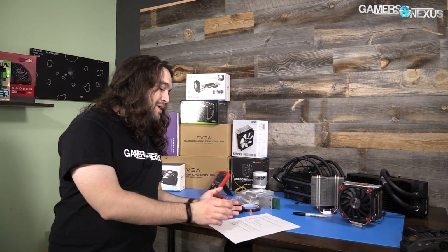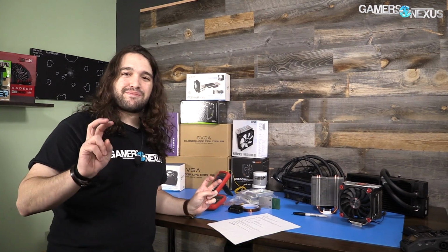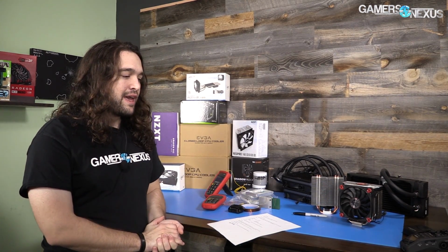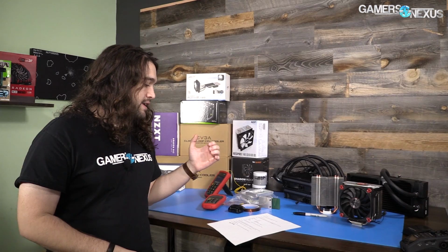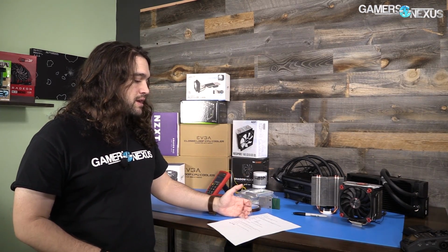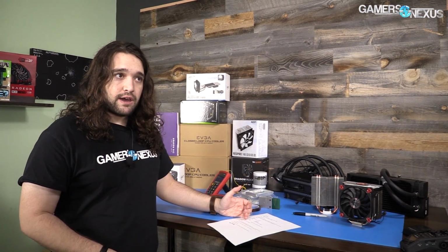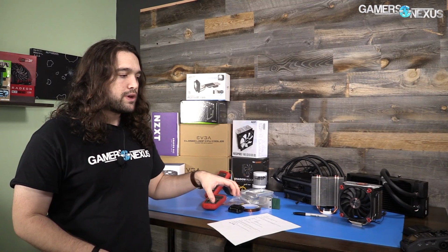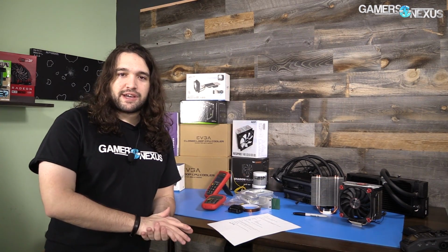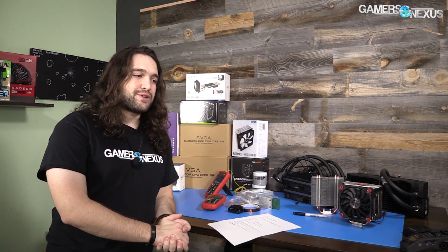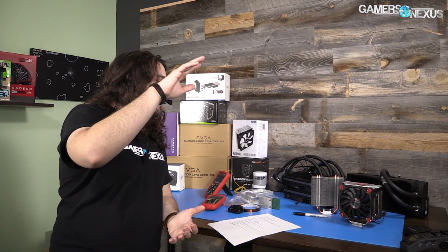Software, my bold note on the sheet: software can't be trusted. And it's true for a lot of things. AMD, for example, if you're running AMD CPUs for your thermal benchmarks, good luck, because they use a different temperature scale, TCTL, and your temperatures with AMD for FX and FM CPUs will look like it can idle below ambient. That is impossible. It is not physically possible to have a lower temperature than ambient with any of these coolers on the table,